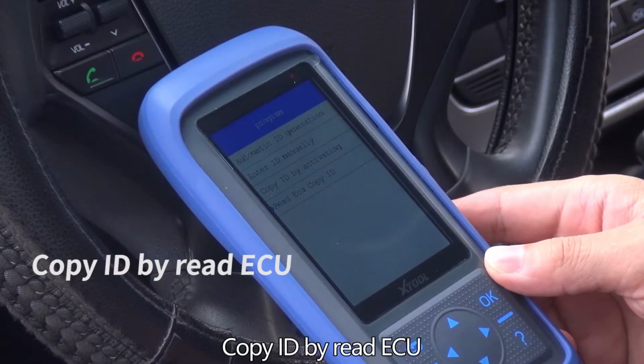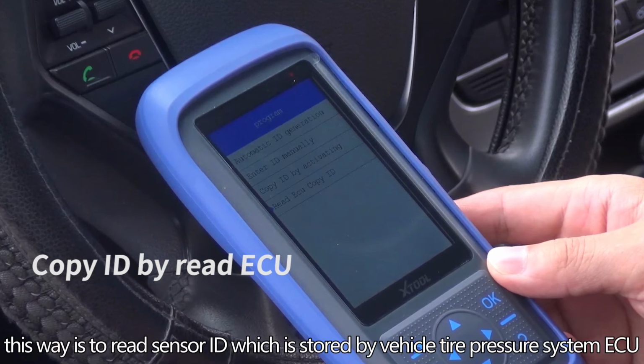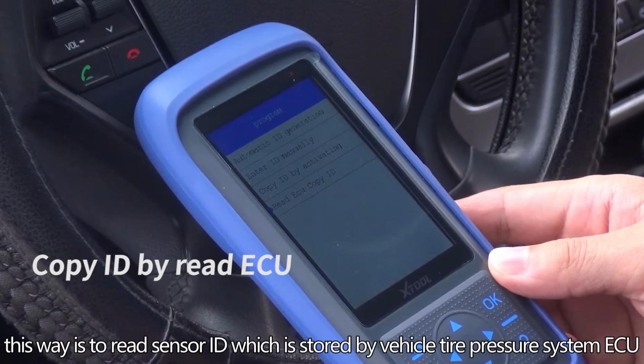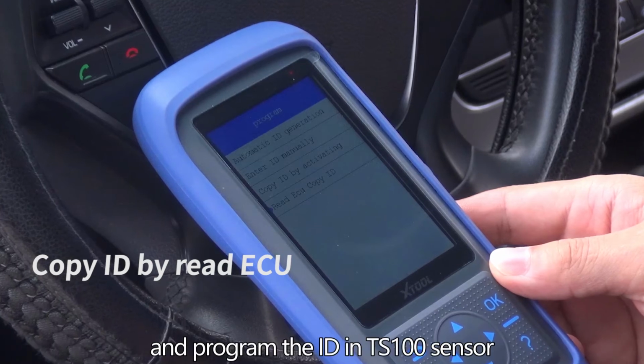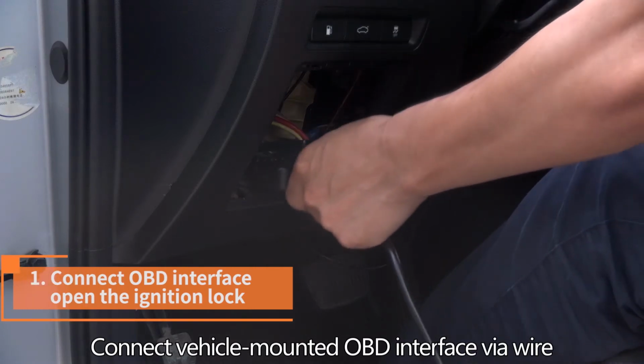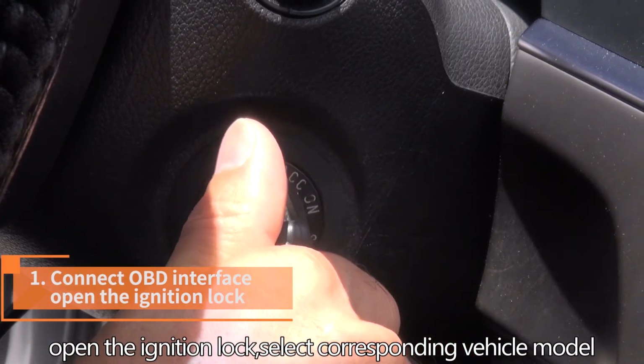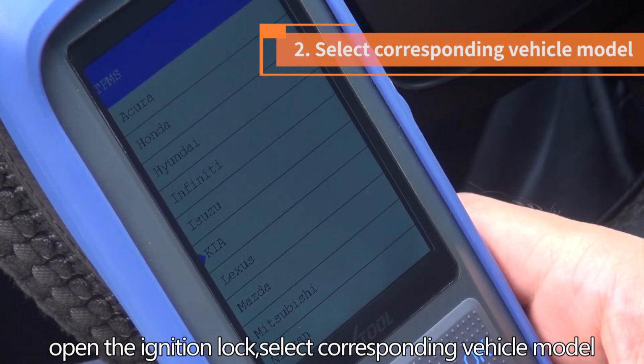Copy ID by Read ECU. This way is to read the sensor ID which is stored by the vehicle tire pressure system ECU and program the ID in the TS100 sensor. Connect the vehicle's OBD interface via wire. Open the ignition lock. Select corresponding vehicle model.